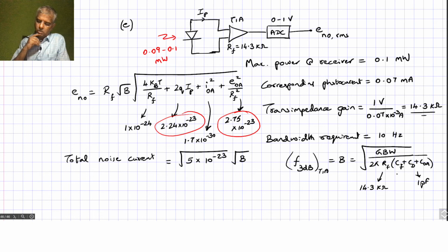When it comes to limiting this, if you look at typical values of CF that you can pick up so that you can put this into a PCB, you will find that this corresponds to about 1 microfarad.